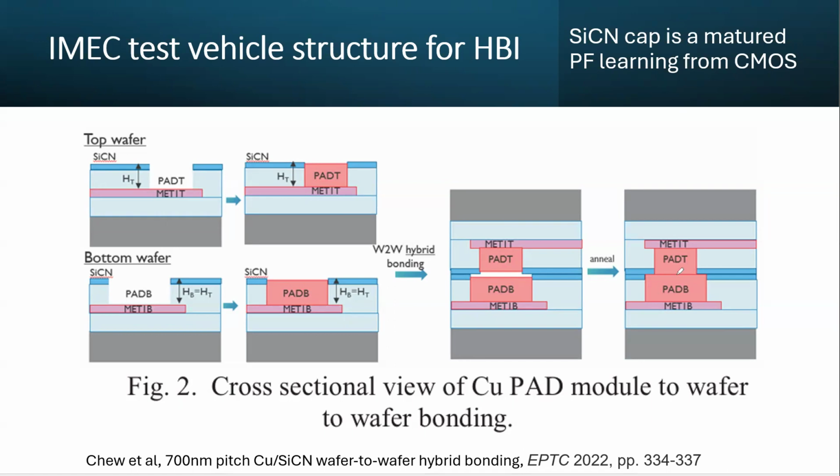By the way, this bonding is pure van der Waals bonding. It's not a chemical bonding. There's no compound formed. It's copper to copper bonding. When you have two perfect same materials together, even dissimilar materials, if they're super clean, they will immediately form a good bonding. And look at that.